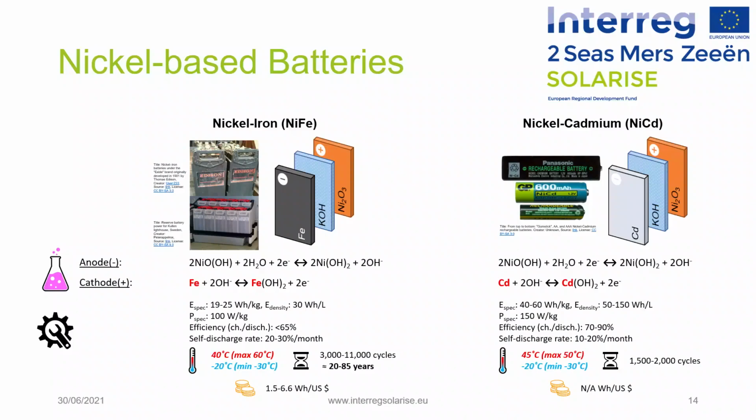While the slow formation of iron crystal preserves the electrodes, it also limits high rate performance. These cells charge slowly and can only discharge slowly. Nickel-iron cells should not be charged from a constant voltage supply because they can be damaged by thermal runaway. The internal cell voltage drops at the start of gassing, which increases the temperature, which increases the current draw and thus further increases gassing and temperature.